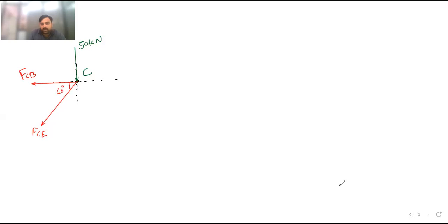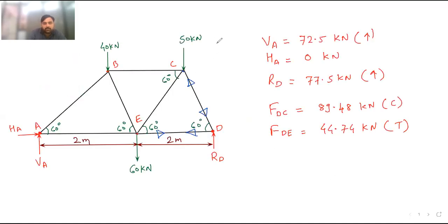Now next, you can see here, while drawing the free body diagram, you should look only at this much of the area. This is the joint C. Only this much of the area you should look at while drawing the free body diagram. Yes, FDE is compressive force.